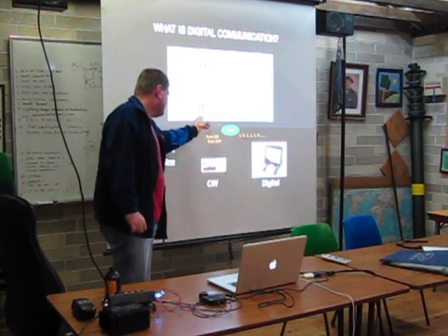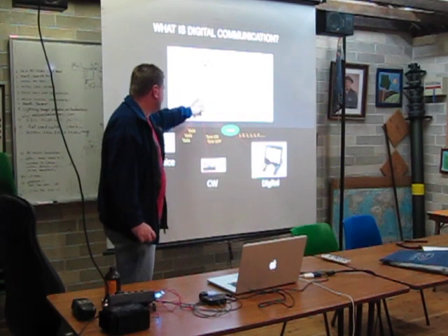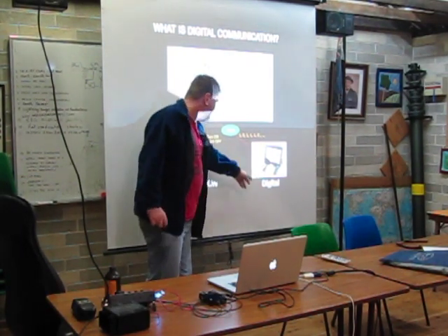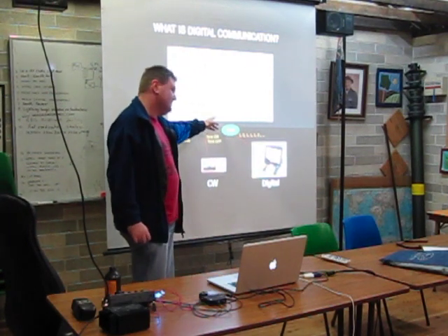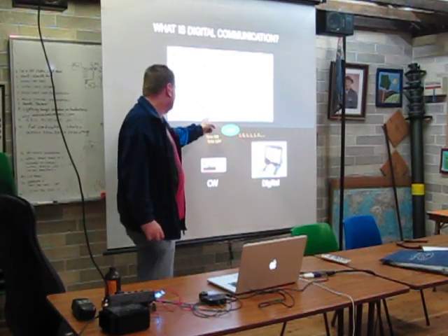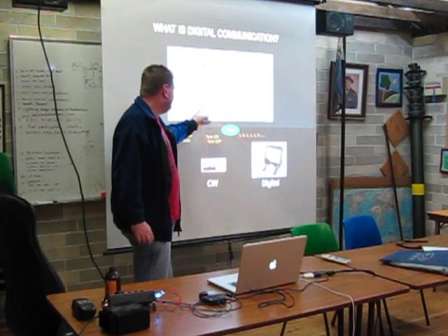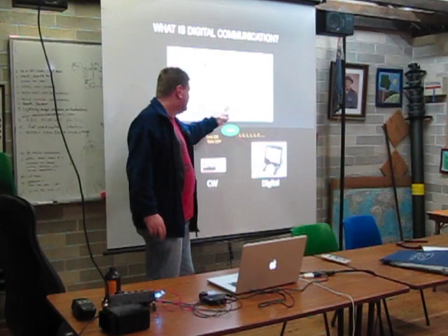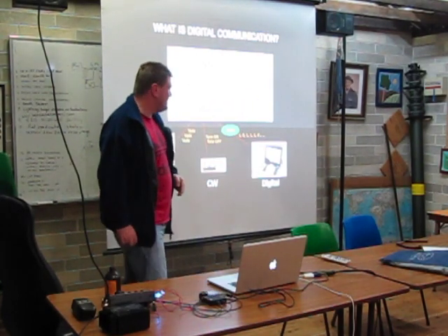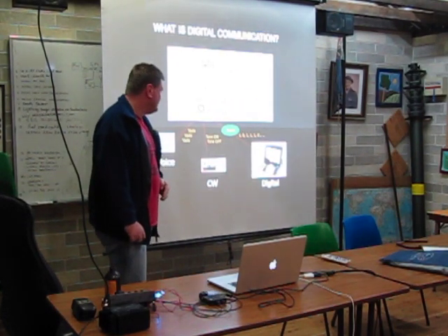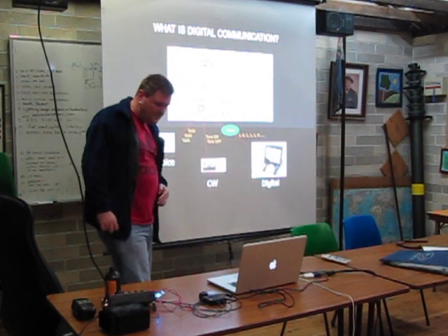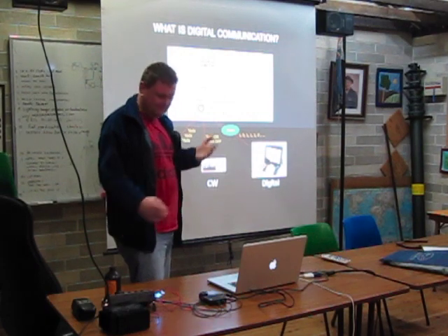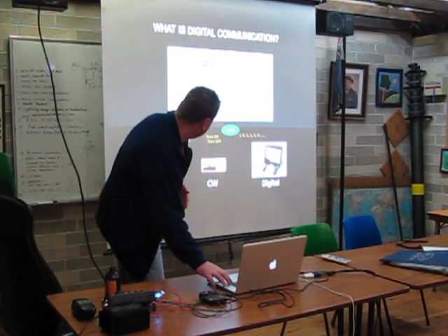If we have a tone switched on and off, the audio oscillator causes a tone to go on and off. You can also plug your computer's sound card into this audio stage of the radio, and then the audio tones that get generated get shifted up into the radio frequency part of the spectrum. So that's the basic principle. Is that more or less clear for everyone? Yeah.